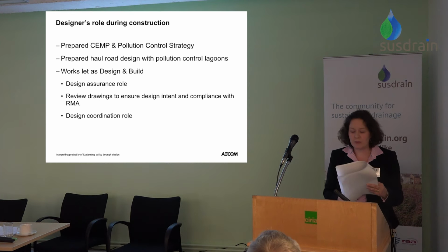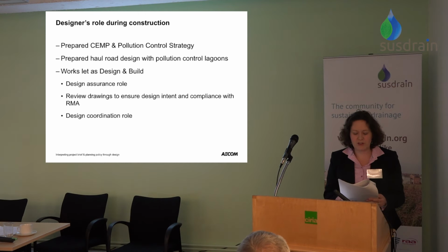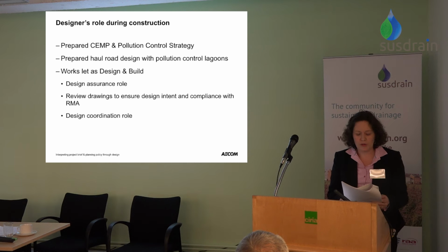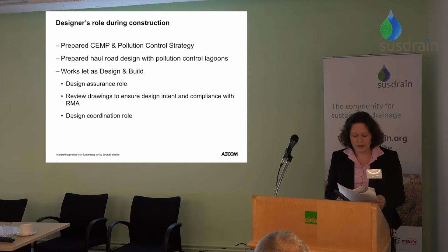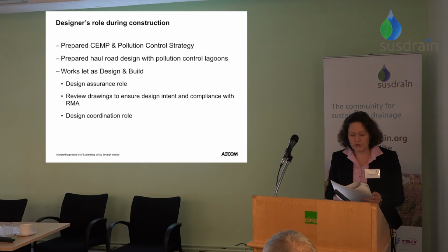The design team continues to provide support to the university through the construction phase. We prepared the construction environmental management plan and pollution control strategy for the wider development to establish the mitigation measures required to prevent pollution and contaminants reaching the Washpit Brook, the groundwater and the SUDS network. We prepared the design for the haul road and incorporated swales and pollution control lagoons in accordance with these strategies to ensure runoff was managed appropriately.